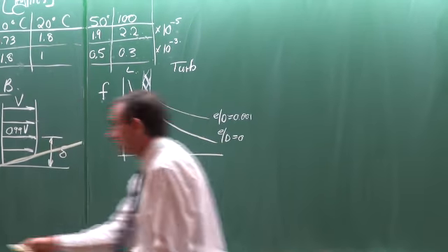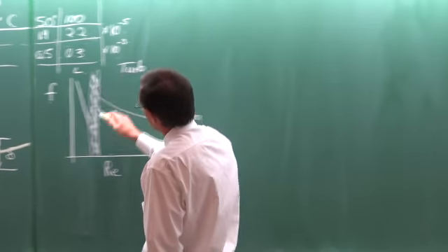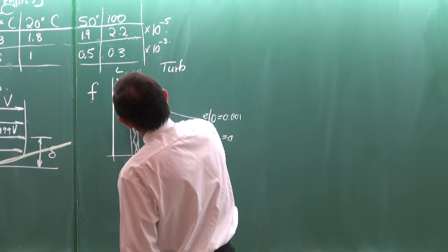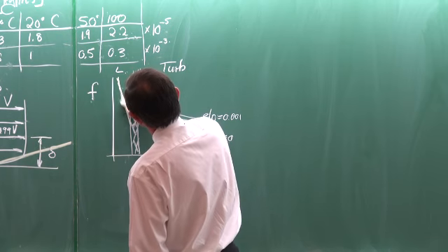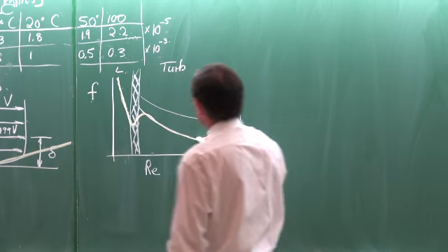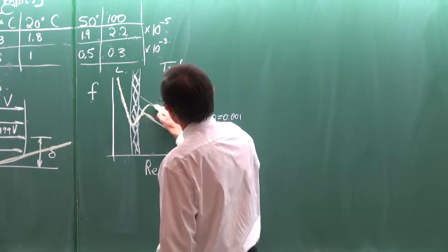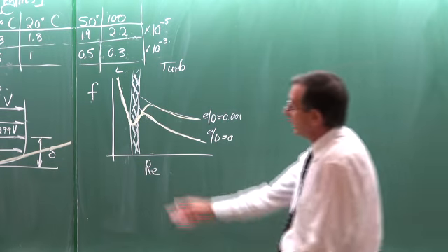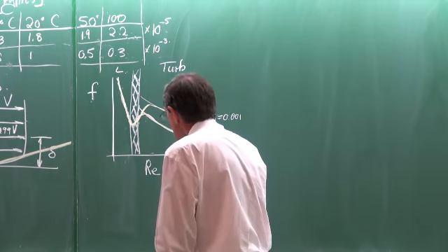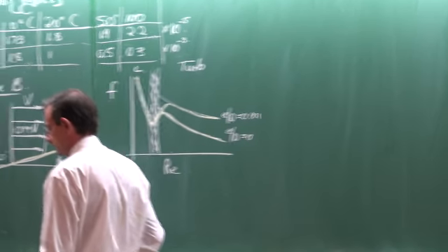It's not a good idea to design in this flow regime, but actually all the measurements these days show that it typically looks like that for a smooth tube, and obviously for a rough tube it would be something like that. So it is very, very highly predictable, and most probably it is time that this Moody chart should be revised and updated.